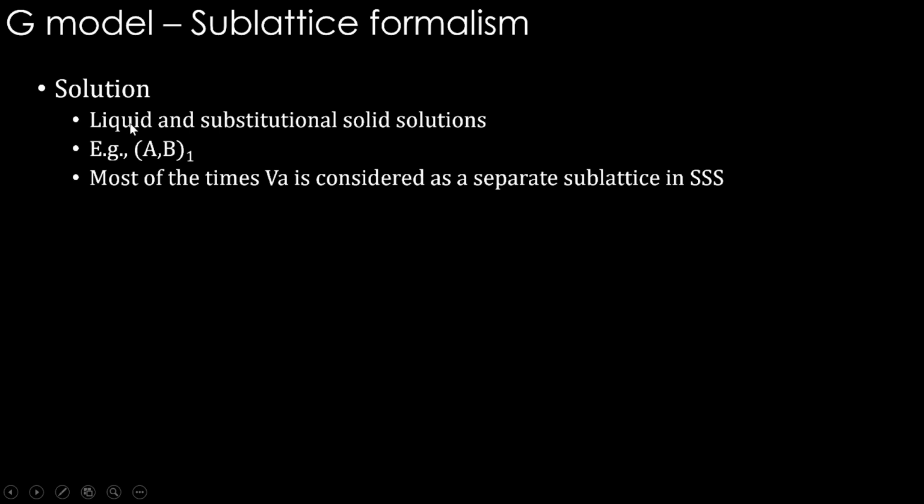What about the other solutions, liquid and substitutional solid solutions? We can have only one sublattice and mix all the elements in that. But most of the times vacancy is considered as a separate sublattice in substitutional solid solution. This is to enable extrapolation, let's say, to higher order systems where the possibility of interstitial elements comes. Also in configurational entropy it has a role to play.